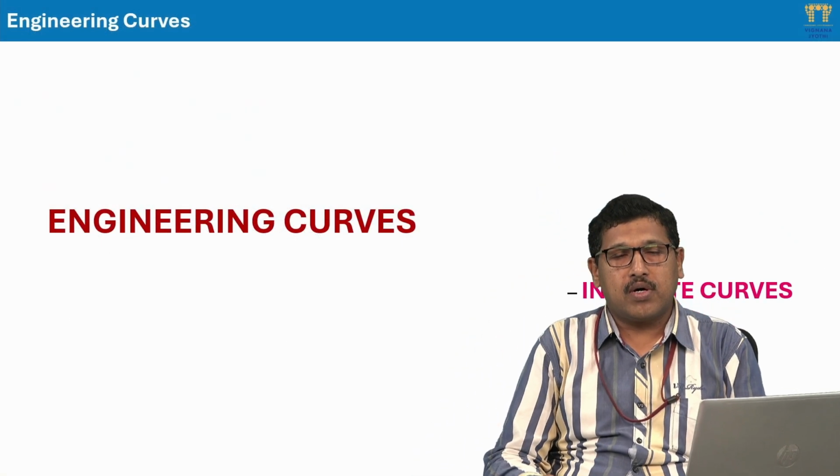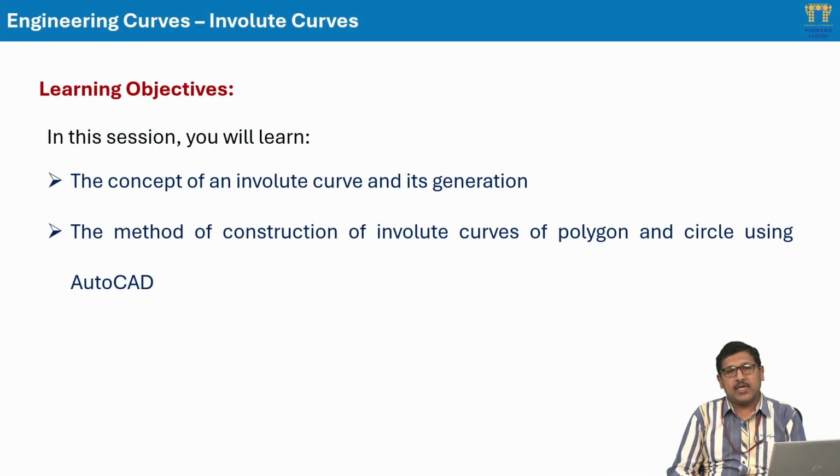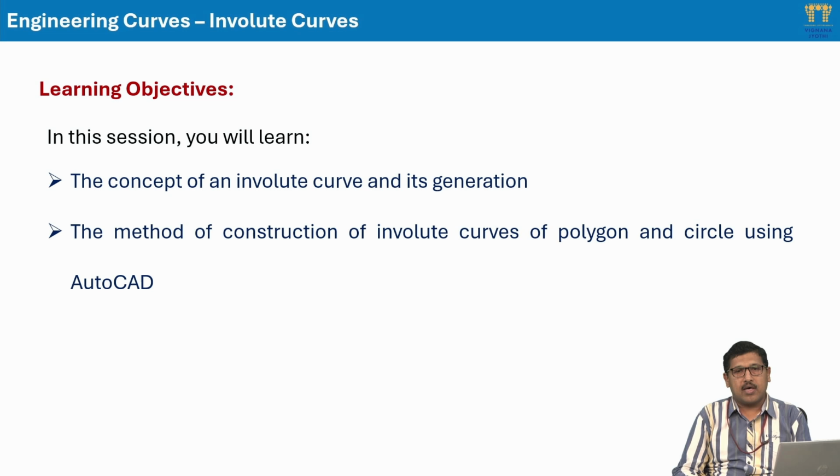Today we are going to learn an important curve in engineering, that is involutes. The objective of today's session will be to learn about the concept of an involute curve and its generation, as well as the method of construction of involute curves of a polygon and circle using AutoCAD software.